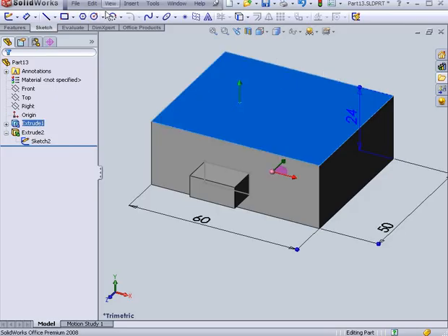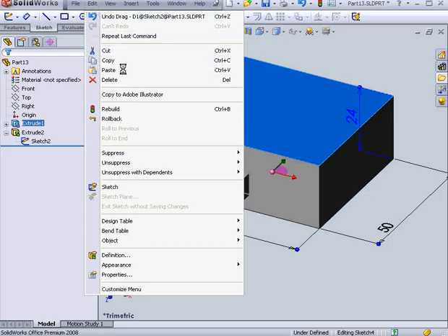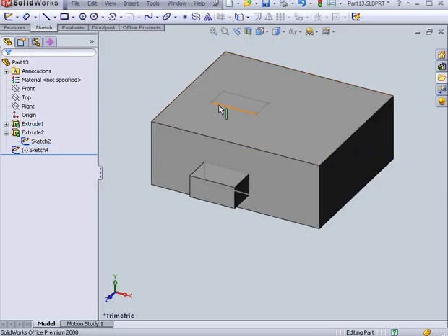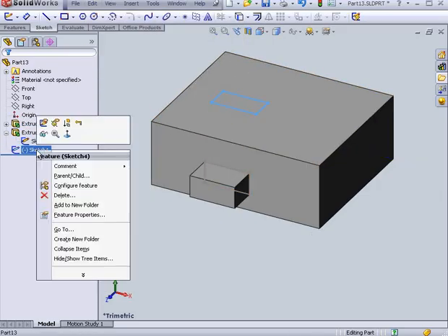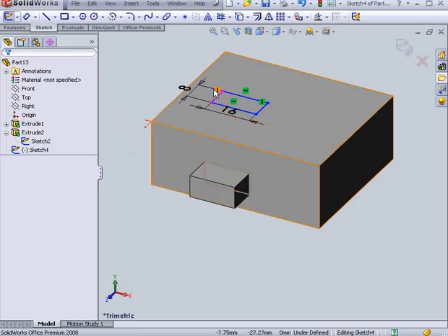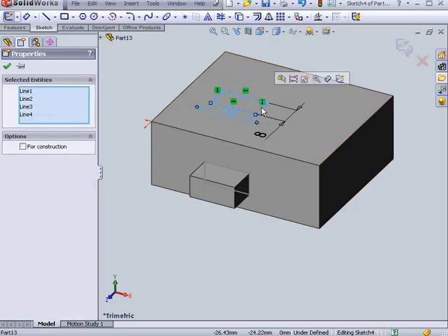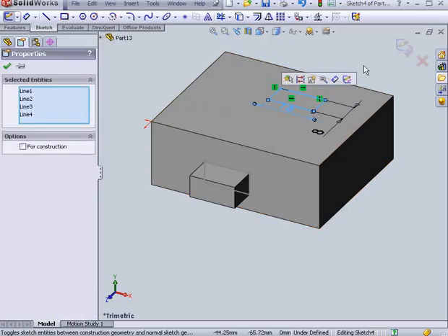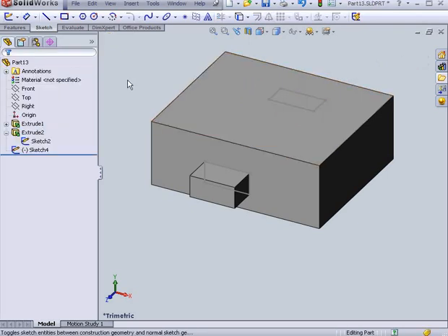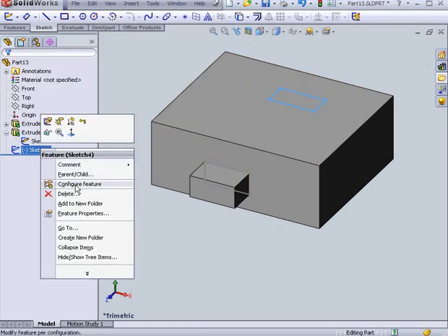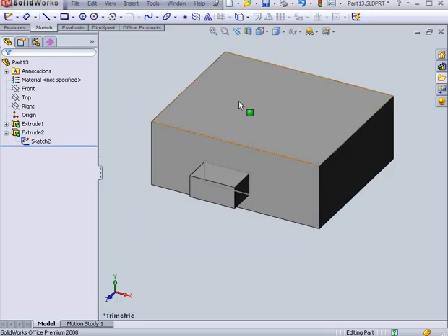face or plane first, and then select Edit, Paste. The sketch will be placed where my mouse selection was. Afterward, I can manipulate it by, let's say, dragging it. Let's exit the sketch, and we'll right-click and delete this sketch.